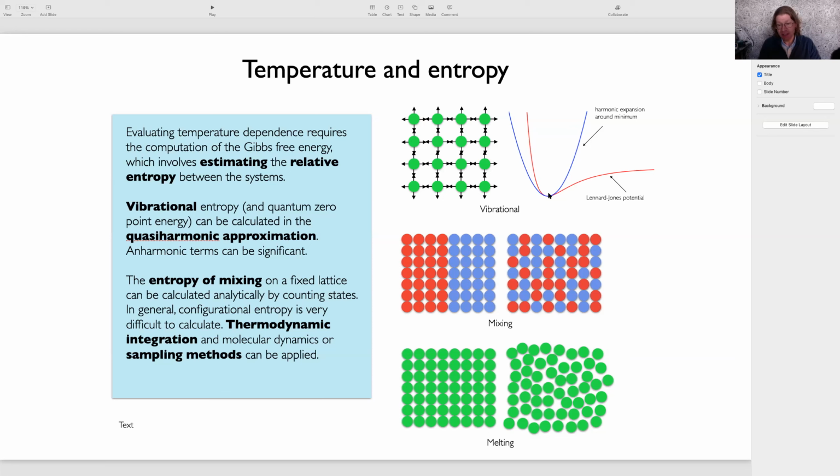This happens sometimes. This is the foundation of dealing with alloy formation and so on. So if you're forming an FCC alloy or a BCC alloy, that's all something you can handle. But that's a kind of special case. In general, atoms' configurational entropy is much more complicated than that. It involves actual movements of atoms off their particular lattice site. An extreme example of that is melting.